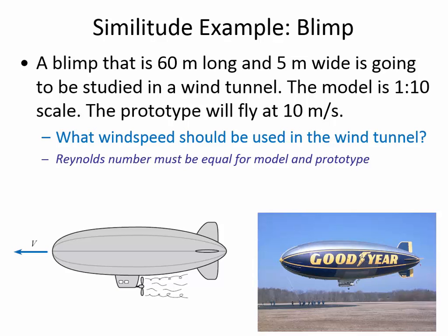The way that we accomplish this is by setting the Reynolds number of the model equal to the Reynolds number of the prototype.